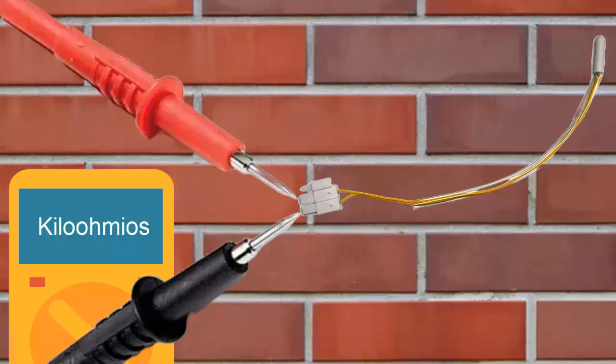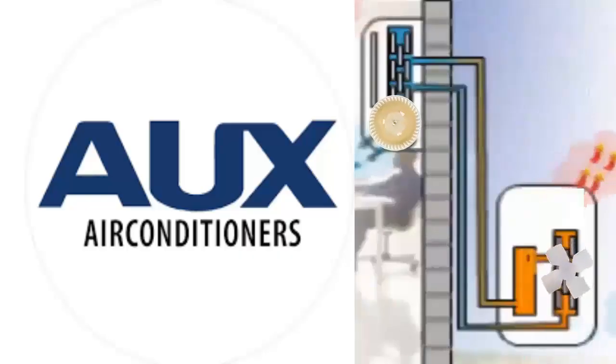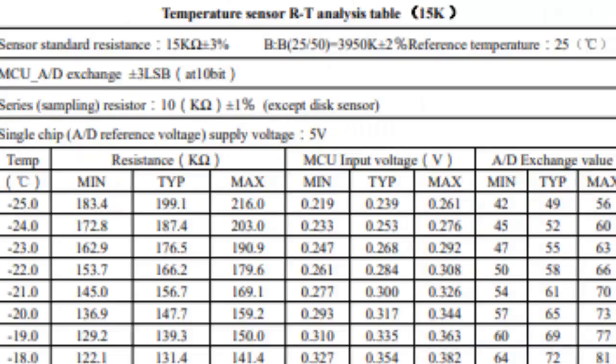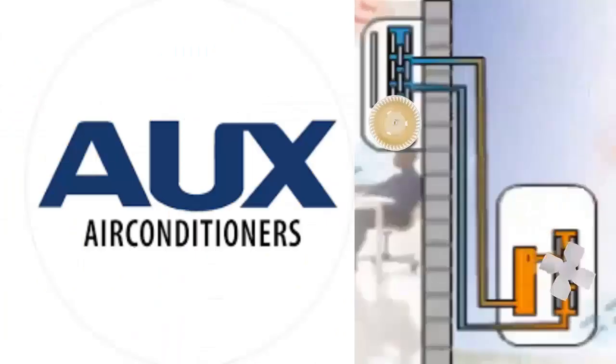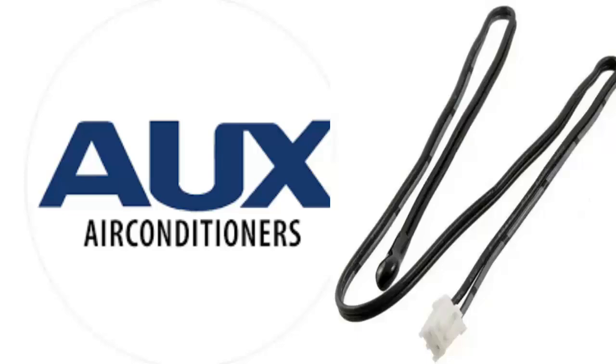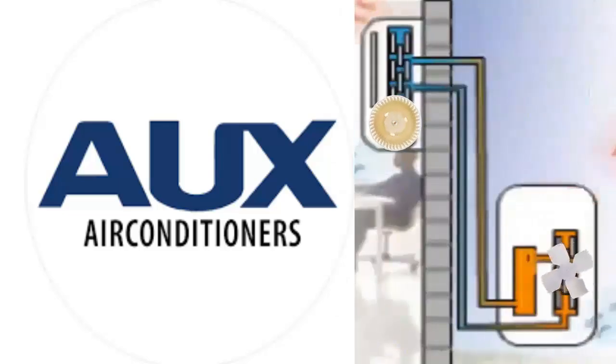7. Compare with the specifications. If you have the equipment's manual, compare the measured value with the sensor's characteristic table. 8. If the sensor shows issues and the error persists, visually inspect the electronic control board that manages the sensor for any faults. Consider replacing the involved electronic control board if the problem continues.